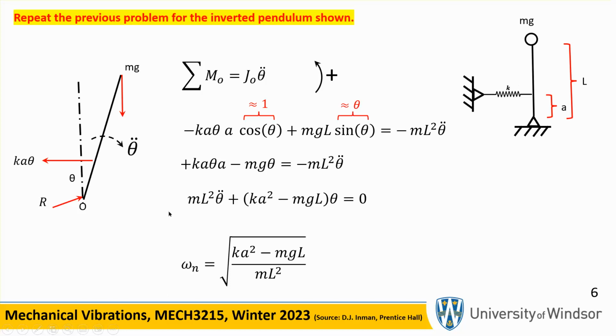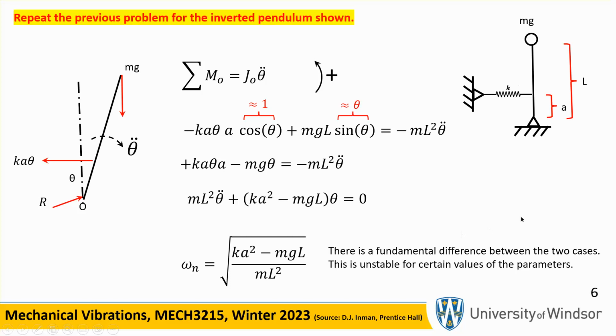It's meaningless. Now, what that means is that this configuration is actually unstable, and it doesn't take you much to see, because if, for example, this spring is very soft, you know that if you tilt this thing a little bit to the right, it will not oscillate back and forth. It may actually drop, completely rotate and go away from this vertical position.